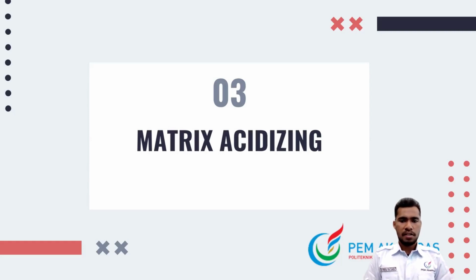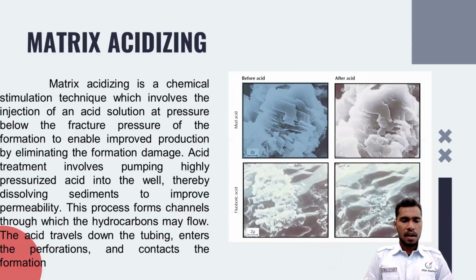It's matrix acidizing. Matrix acidizing is a chemical stimulation technique which involves the injection of an acid solution at a pressure below the fracture pressure of the formation to enable improved production by eliminating the formation damage.